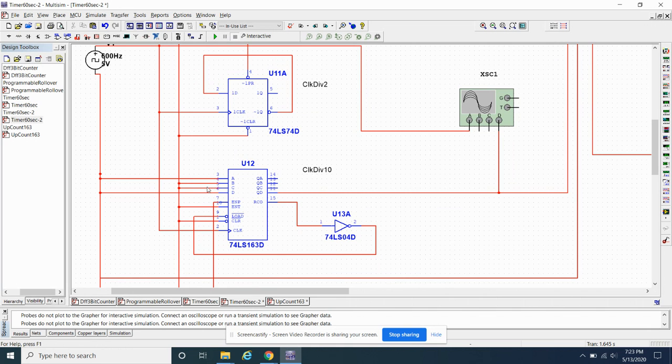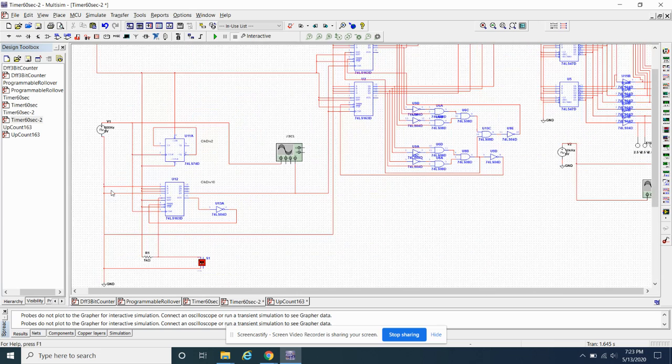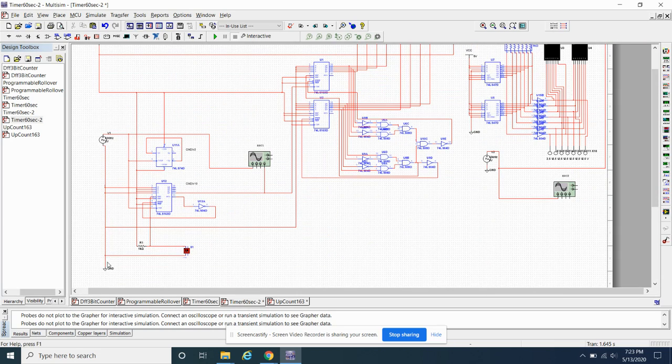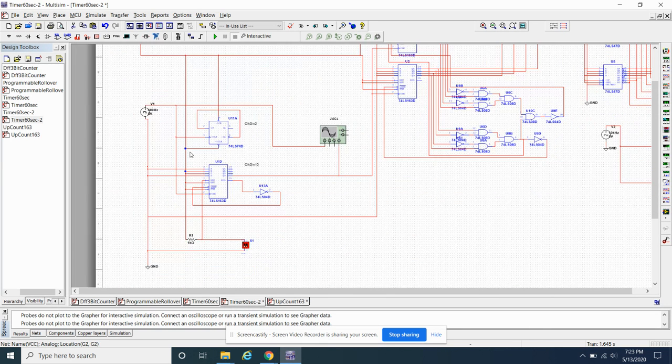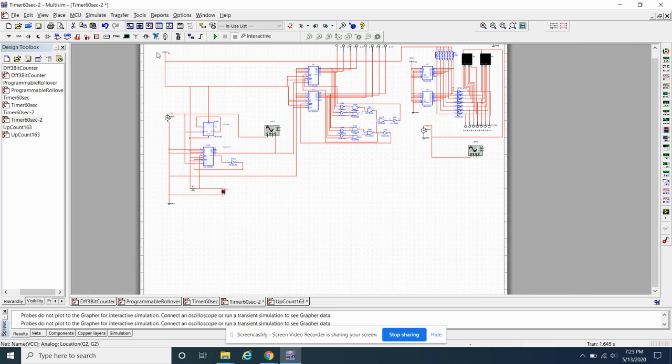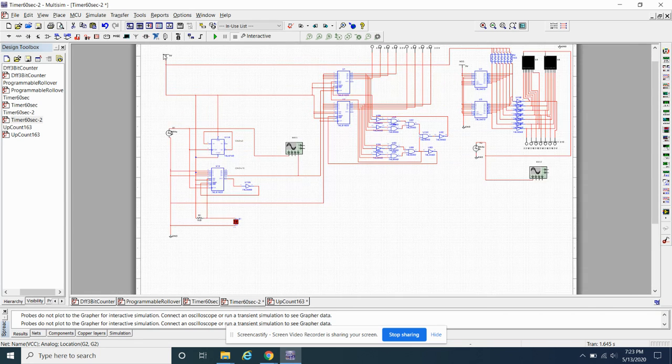So in other words, if I make this a 6, and I can see that it's 6 by looking here. This down here, that's ground, right? So that's a 0. So I have a 0 on my A. This is my least significant bit, A. That's 0. These two are tied to VCC. So if you go way up here, there it's at VCC.